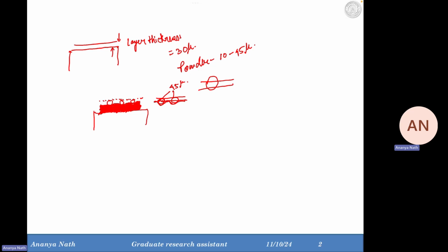The smaller particles, towards 20 or 10 micrometer, will fill the voids, because our D90 is maybe 33. This is my 33 powders. This is my 20 powders. And these are my 10 micron, which will fill the void inside it. So this is how the distribution is useful.